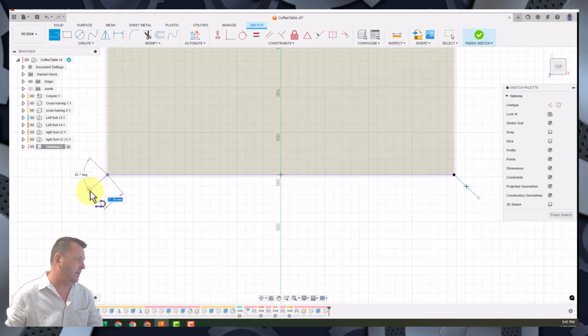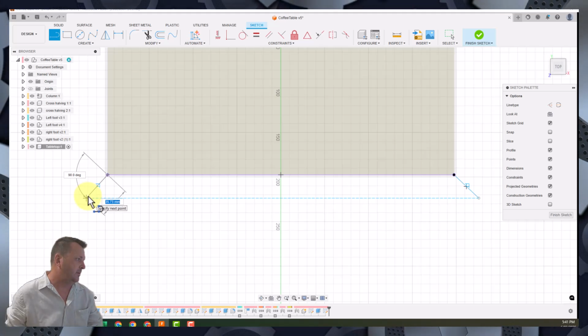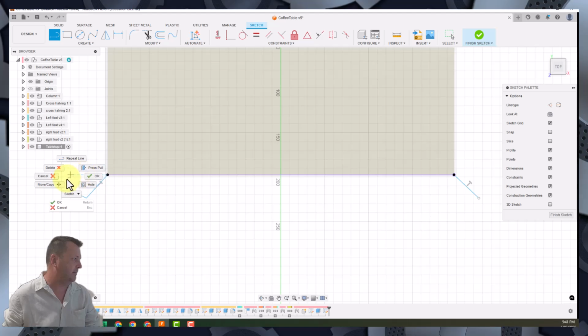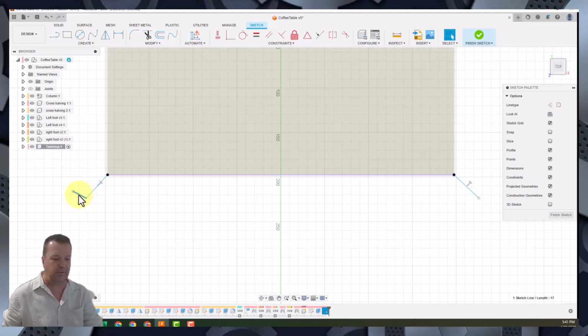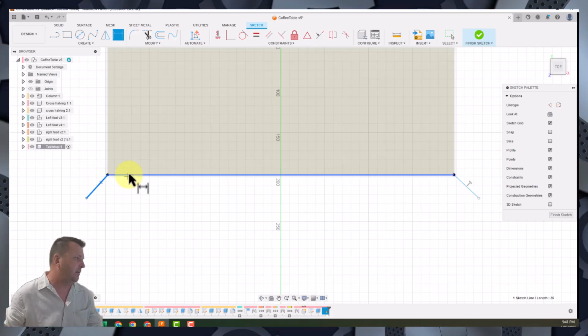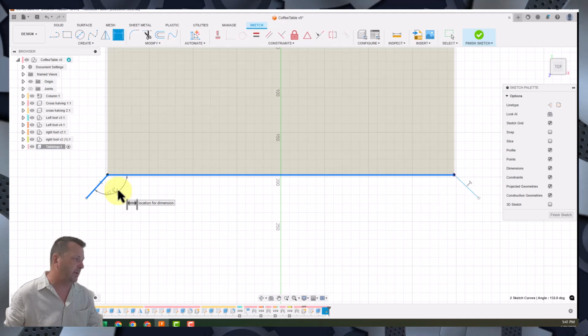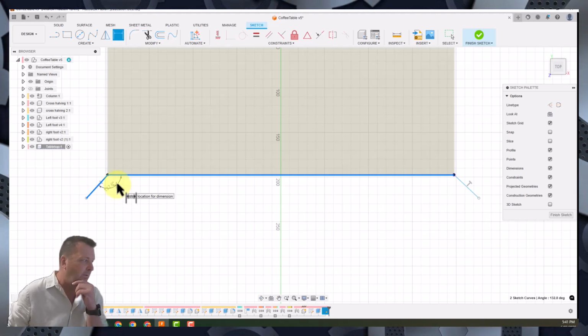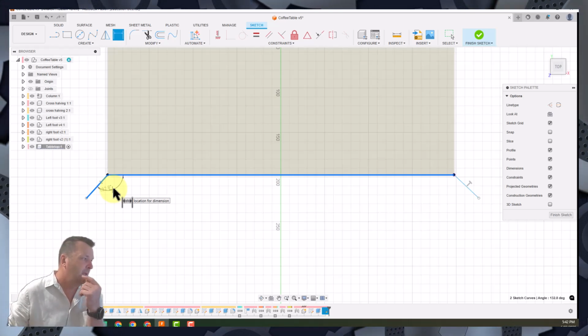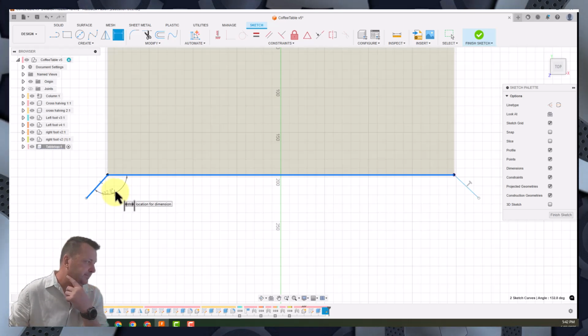And we are going to do one out this side at 90 degrees. All right, so I'm just going to do that like that. Put an extra line in there that we don't need, so we're going to clean that up. Cancel, select that, press delete. Now if you want to do angles, you can do angles with your measurements. So we can select one line there and one line there. Most of the ones that we have been doing, you will have noticed that we have just been doing straight lines, so now we're doing this. So you can do angles like that as well.